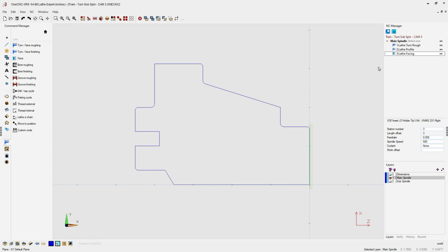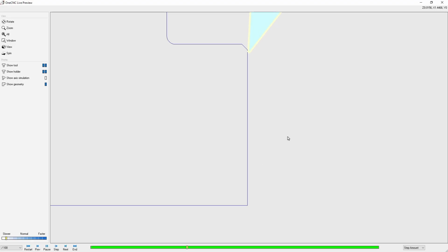Let's take this into the toolpath preview. We're going to right-hand mouse click, select Preview Toolpaths, and now you can see we've performed a small little rapid move of 50 thousandths, 100 thousandths feed in, 100 thousandths pass, and then a retract move of 50 thousandths along the z-axis. Much more efficient.